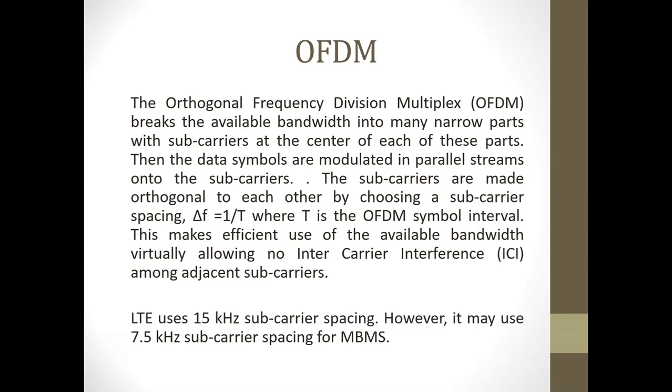If you have two users in the CDMA, okay, on two OVSF codes, then as we showed, if we ignore the background noise, then actually the users, say A and B, don't disturb each other. So now if you stop the operation of A and let only B operate, then B has the same kind of experience.